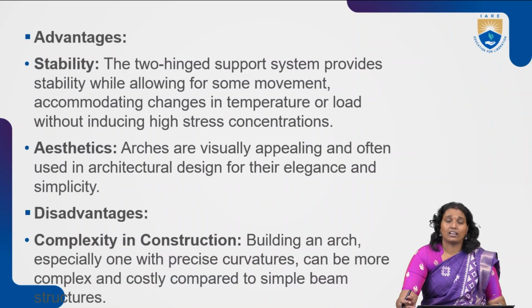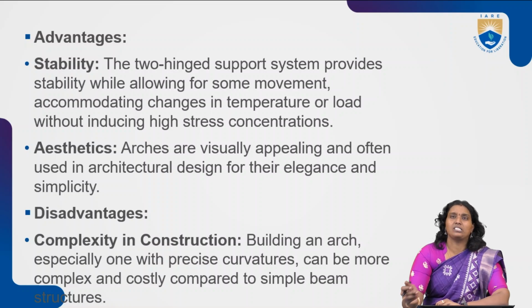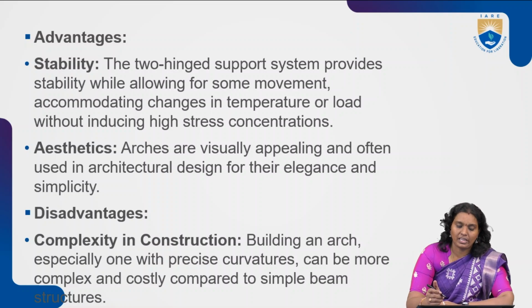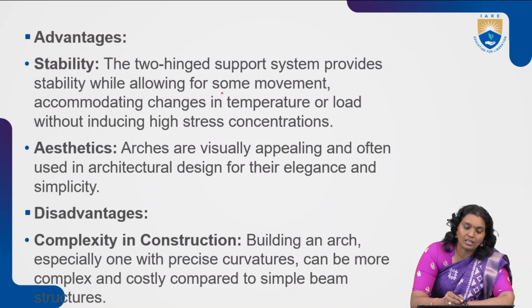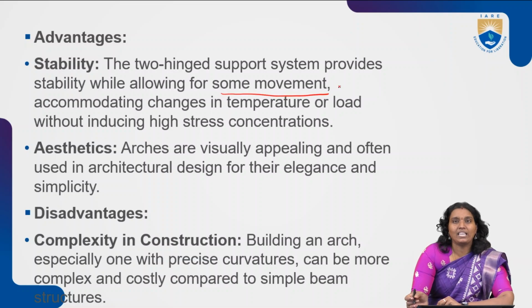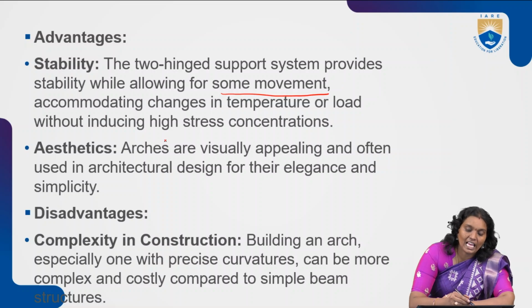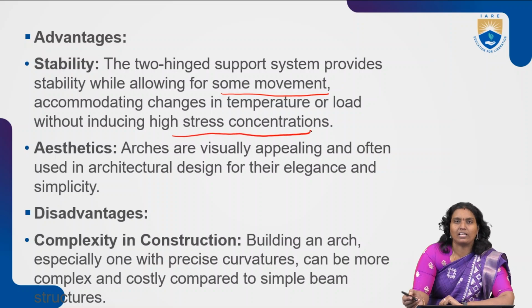Moving on to the advantages. Here, the stability: the two-hinged support system provides stability while allowing for some movement, accommodating changes in temperature or load without inducing high stress concentrations. Also, arches are visually appealing and often used in architectural design for their elegance and simplicity.